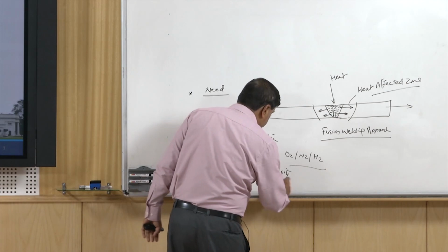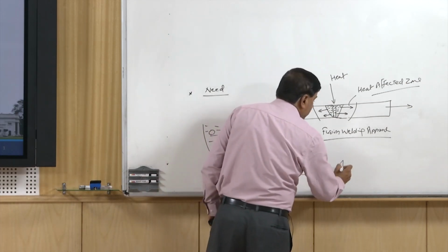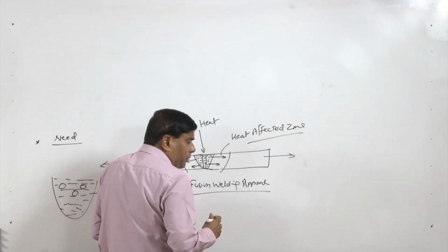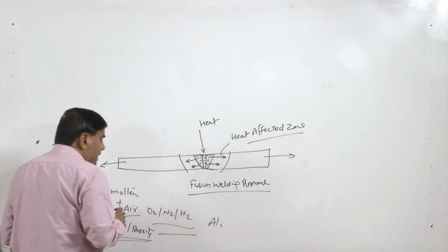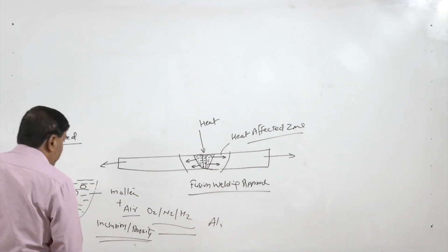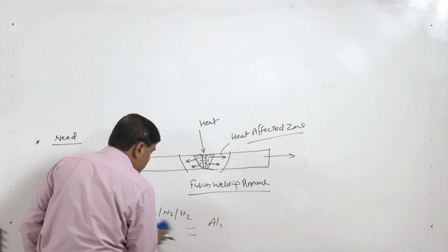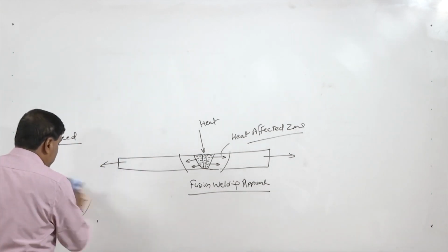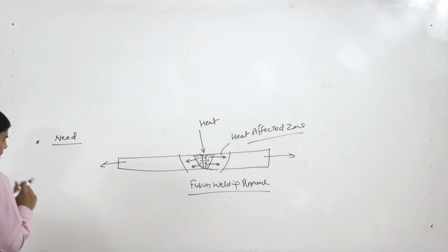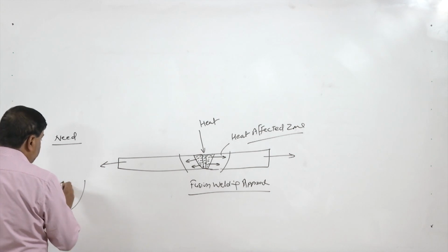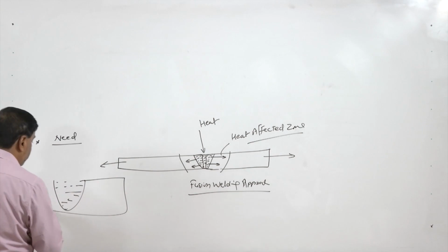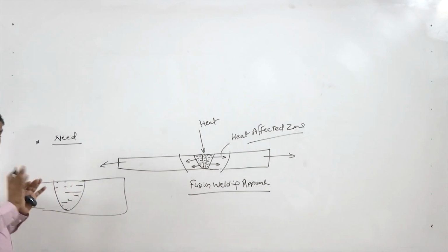So, these problems especially in case of aluminum welding or wherever high speed welding is carried out of even common metals, it poses the problem of the porosity and the inclusions. Apart from the problems related with the atmospheric gases, sometimes the typical nature of the solidification during the welding and the heat delivery in fusion welded joints poses two types of problems.